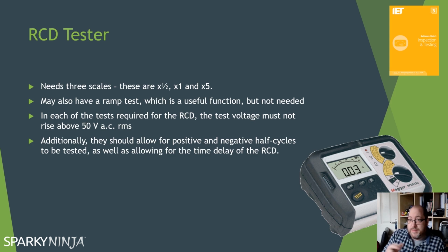The second way is the manufacturer. The manufacturer will have an inbuilt limit of 2 seconds. So you may notice that your times half doesn't actually come up as no trip on the instrument. It might just say greater than 1999 milliseconds, which is 2 seconds. So the manufacturing standard implements a test limit of 2 seconds, just in case we have these increased potentials of voltage in the local earth arrangement.